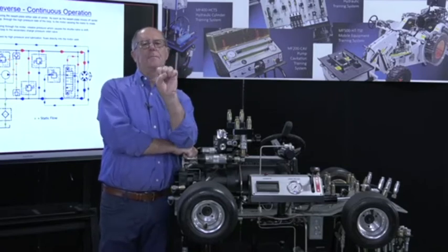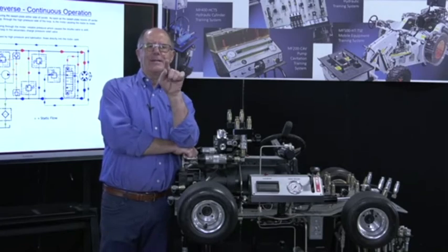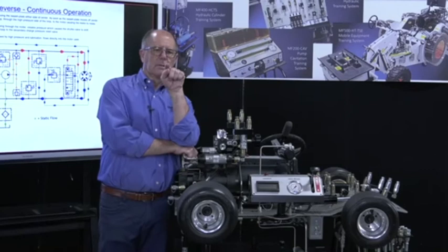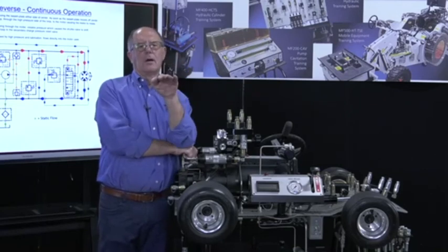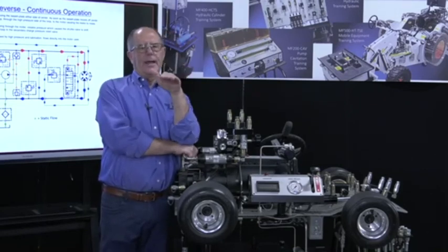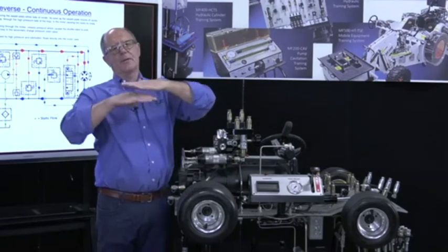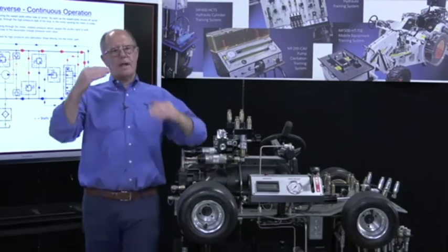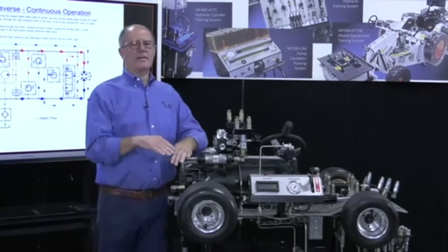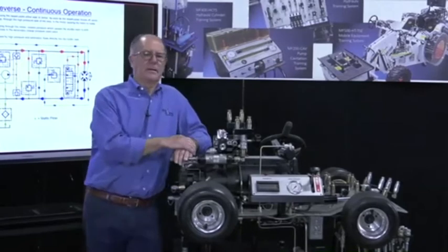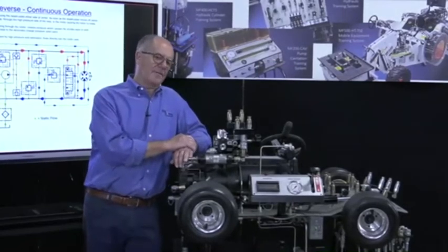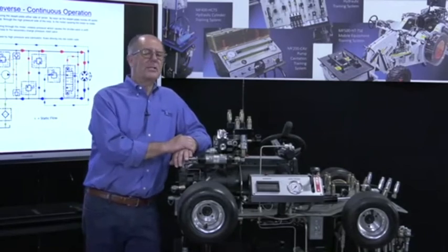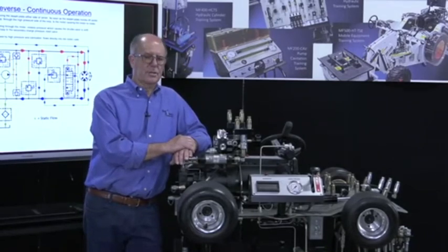Why? Because when you crimp a fitting, it leaves a little dent in the hose inside. So if you blow a projectile through there and it gets to that point, it's going to drive the contaminants down into that little, let's say, potentially do this, because it could have an edge, right? And it's going to drive the contaminants into there, and you're going to think, well, this is going to be clean. Be very careful of those kinds of things. I'm not saying it's impossible. All I'm saying is that it's not always the right solution.